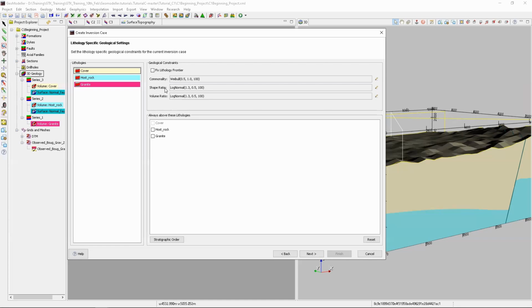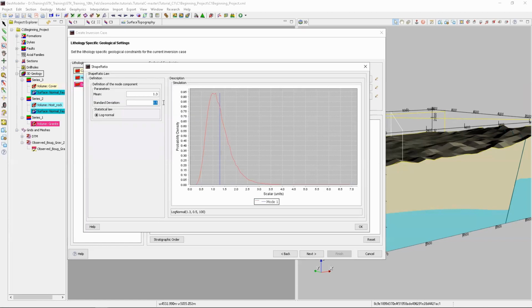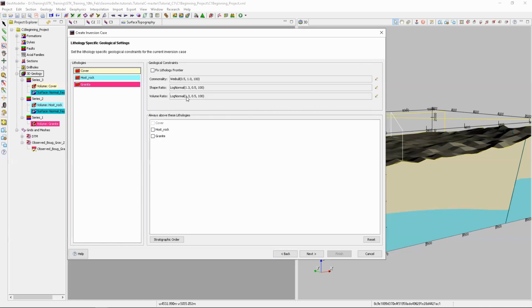If you want your inversion probable model should not give you the rough surface on the body, you can restrict the standard deviation very tight, like 0.001, something like that. Otherwise, if you are allowing the standard deviation large, that means you are going to get a very rough surface of your predicted model or your optimized model.